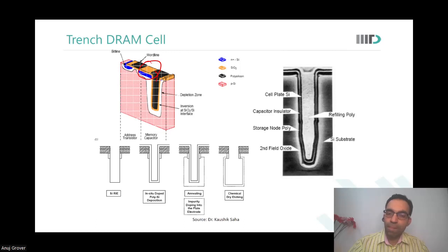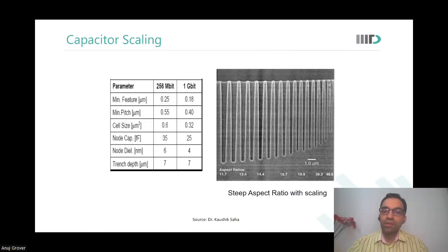The trench one is actually complex in designing, and you see this is how the DRC is defined. The aspect ratio, if I keep the trench to be wide, I can go very, very deep. My capacitance can be large, but I lose area. If I do not want to give area, then due to the very nature of it being a trench, I go to lesser depth and my capacitor reduces. This is intuitive. When we wanted to use larger capacitance, we were ready to probably give more area also.